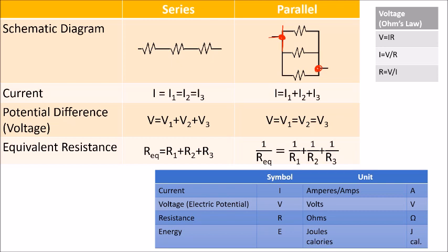Whether something stays the same or is different will depend on whether we're in series or parallel. In series, the current stays the same, and in parallel, the voltage stays the same for each branch. In series, the voltage, we can check our individual calculations by adding them together and seeing if we have the total voltage.